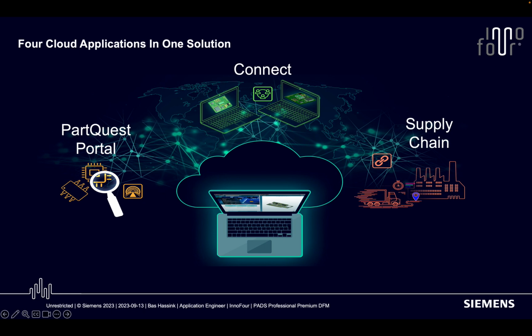Connect is the cloud-based workspace that brings teams together where you can efficiently manage, share, and visualize PADS project data. And PCBflow DFM, giving you access to state-of-the-art DFM analysis fully integrated in the layout software. Projects that are saved in PADS Connect can undergo DFM analysis quickly and efficiently using DFM rule sets that have already been configured by manufacturers and industry leaders.